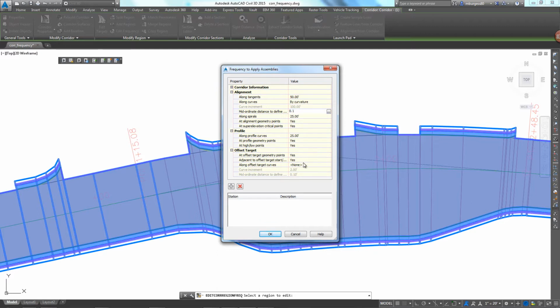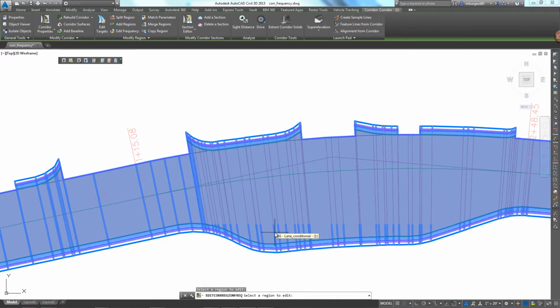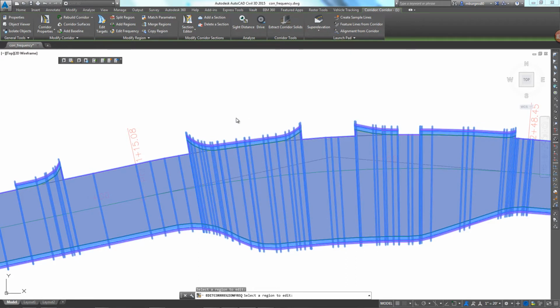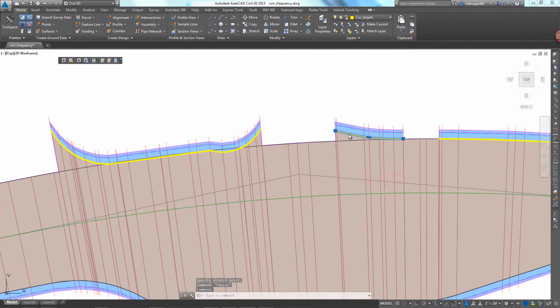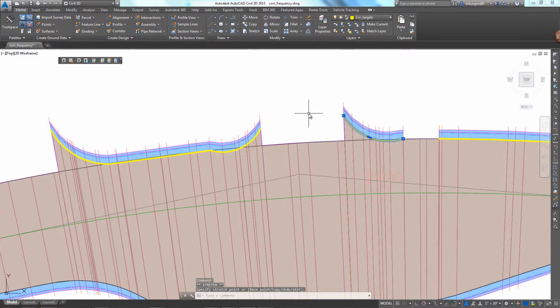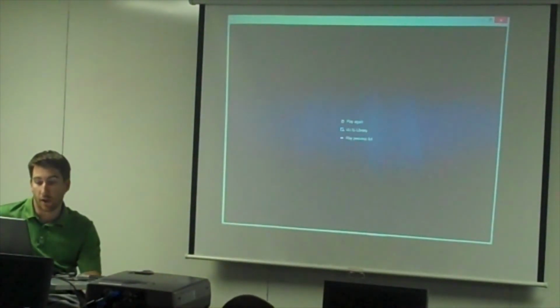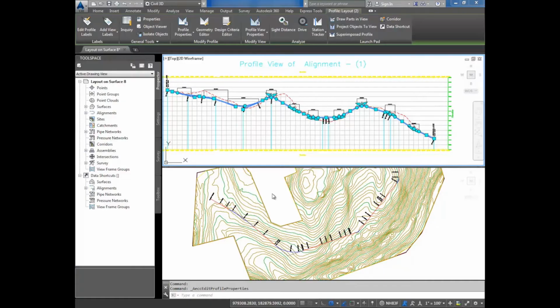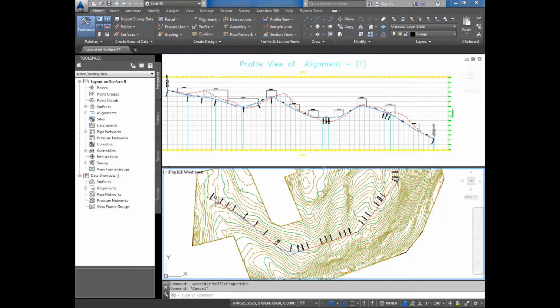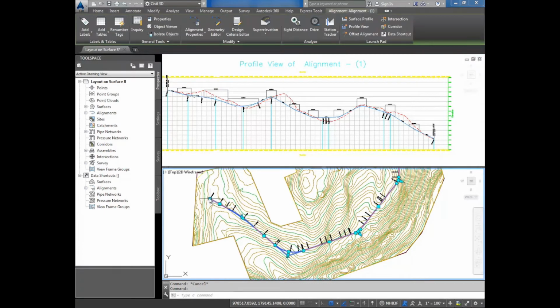So this allows it to monitor the distance along those curves and create points where appropriate, and you'll see it add a bunch of additional slices to tighten that up so when they go to survey it, it works better. And then you want some real-time adjustment, to be able to adjust those target lines more easily on the perimeter, and then have your corridor, your 3D model, effectively update. That's going to drive your quantities, it's going to drive your sheets and everything.